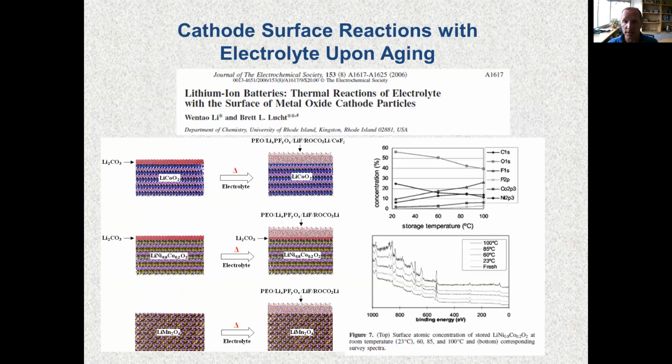And so what this suggests is on the cathode side, while there may be some oxidation reactions of the electrolyte on the surface of the cathode, and certainly if you start charging the cells to high potential above 4.1 volts versus lithium metal, there are more oxidation reactions. However, some component of the reactions that were observed on the DOE program cells is related to just the thermal decomposition of the electrolyte and the reaction of these thermal decomposition products with the surface of the cathode.